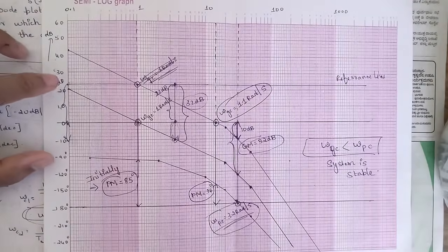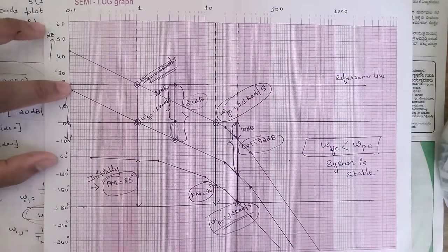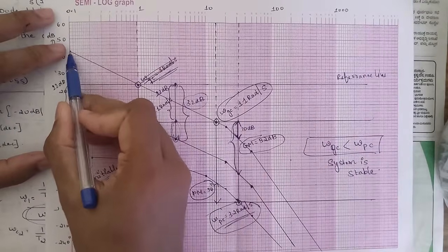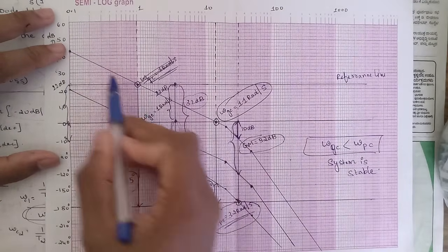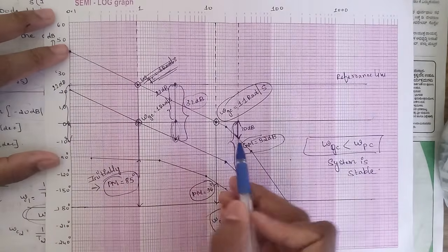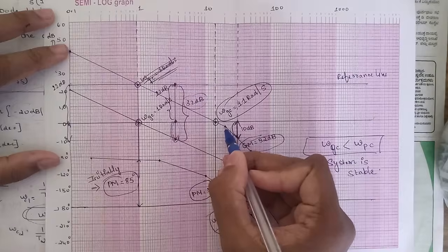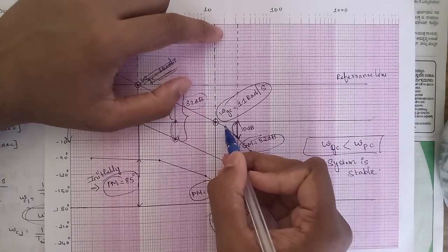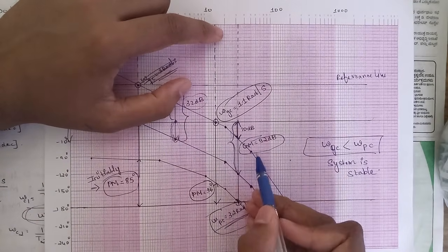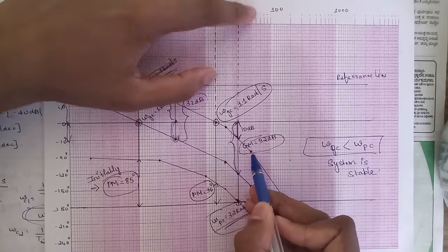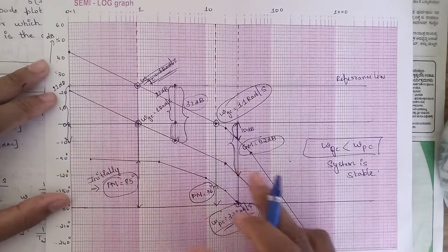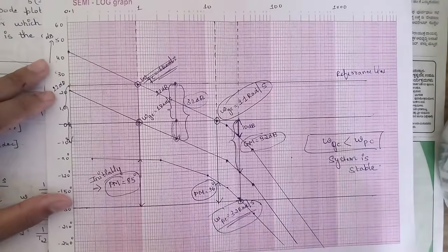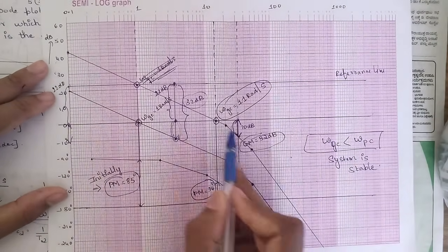So using this 22 dB reference line, for the same data try to draw a slope here, starting from 0 radian per second. Draw a slope which touches up to 20 radian per second first, then change the slope to 40 dB per decade, and it touches up to 50 radian per second. And from 50 radian per second draw a slope of 60 dB per decade. Okay, so this is the new magnitude plot which I have drawn.